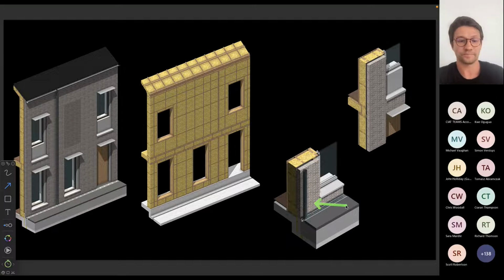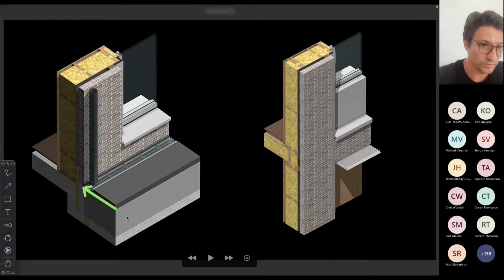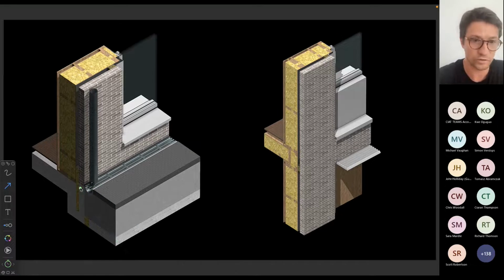can also serve as a dead load element to receive the facade. So we can have some kind of an upstand, or just a part of the foundation, where the brick is stacked on, and it's laterally loaded on the primary framework, which in our case is timber.